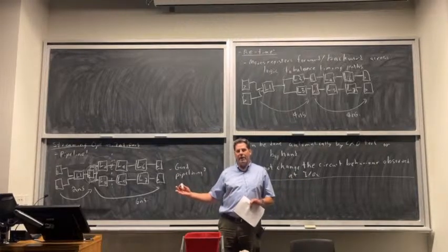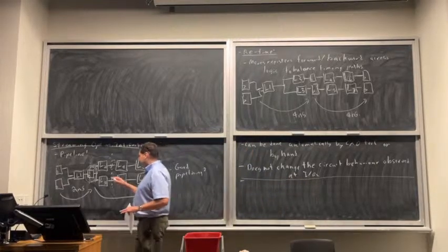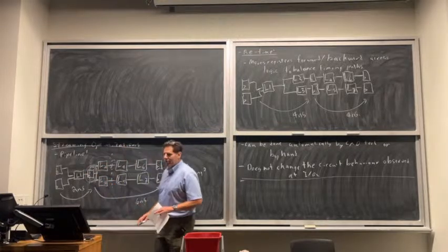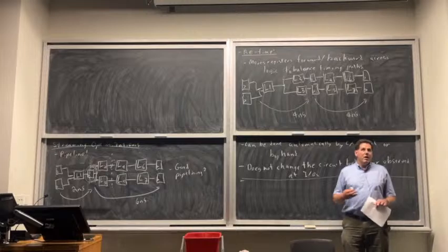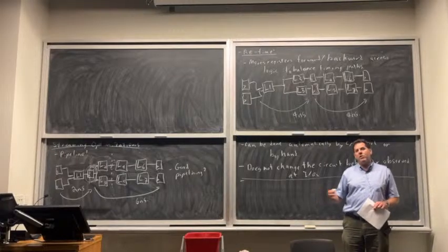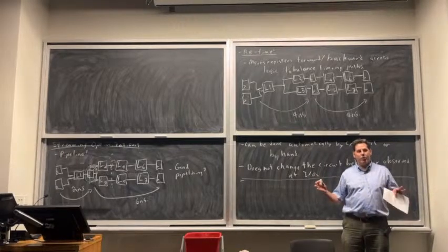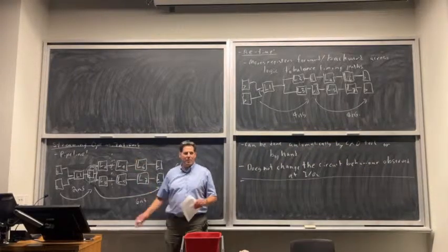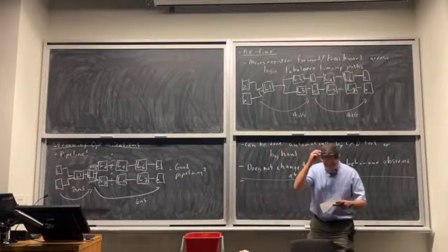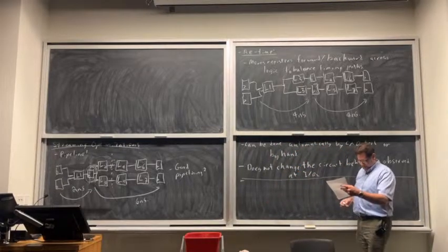Later on in the compile, they can fine tune, but it's hard to integrate the changes. If you give them a better starting point, your results will generally be more robust and usually better. You've helped the CAD tool by giving it a better starting point because they're not perfect at this kind of retiming. So it is still a useful thing to do. Does that make sense?